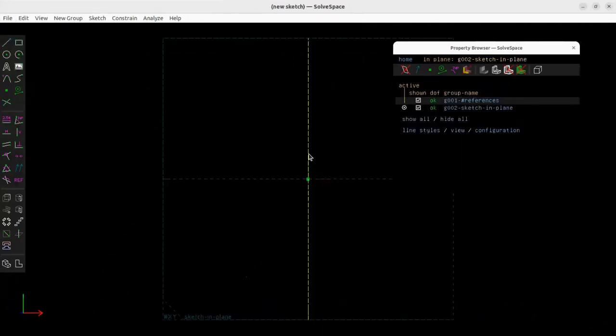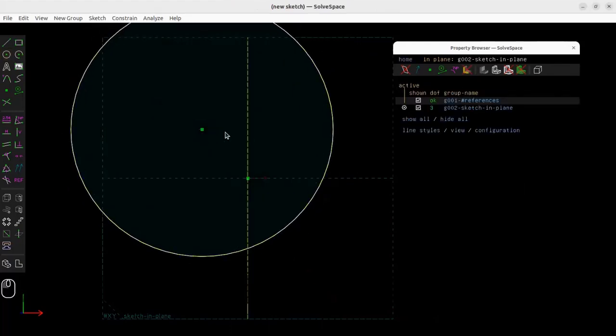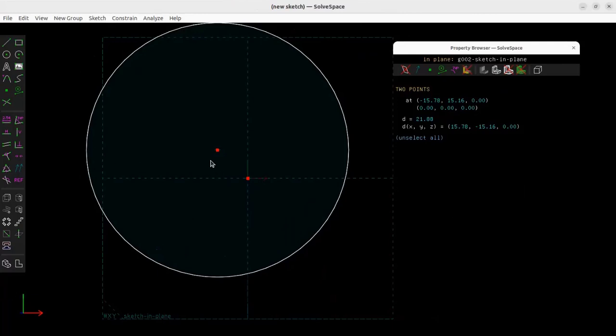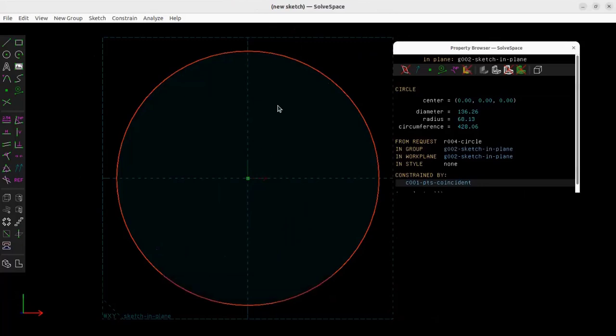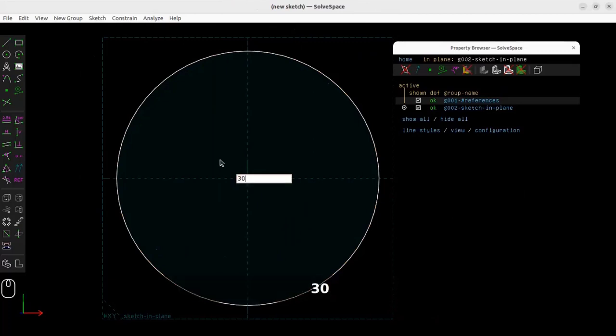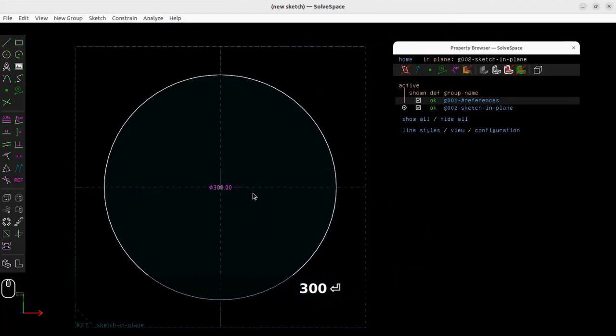And next we create a new file because we need to create the top part of it. And yeah, you guessed it, it's this round part. So we can snap it to the center just by selecting the center point of both our coordinate axis and the circle. So point. And we can give it a diameter. So the diameter is 300, like so.